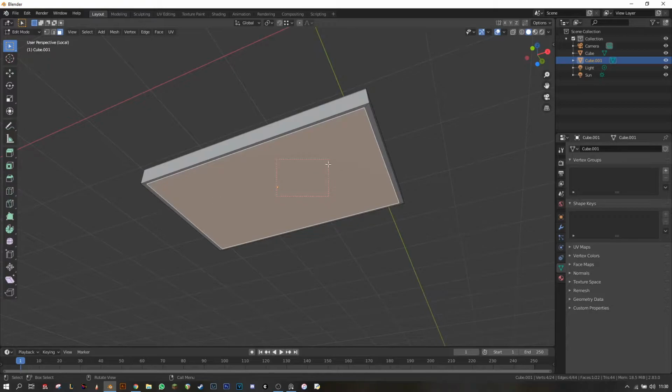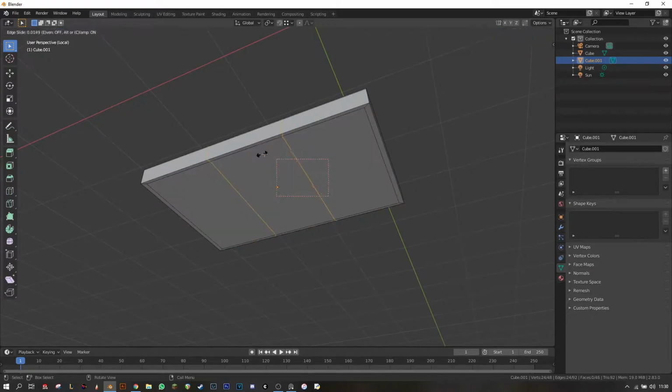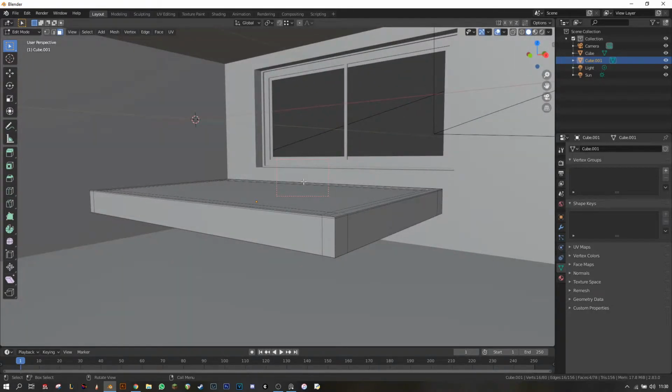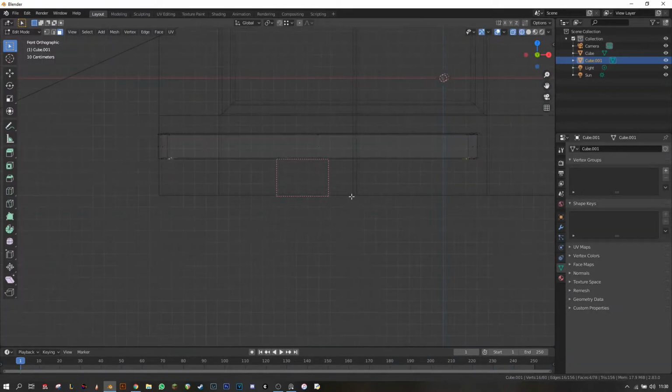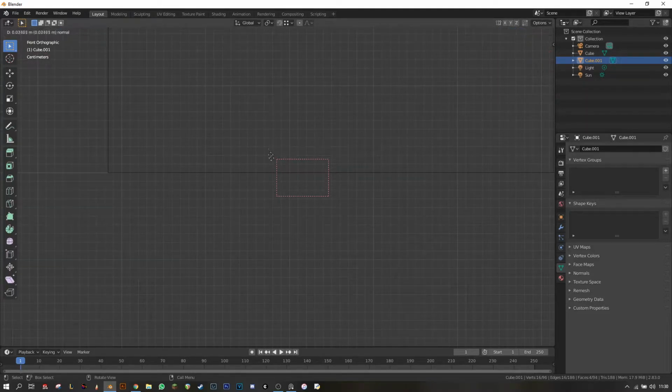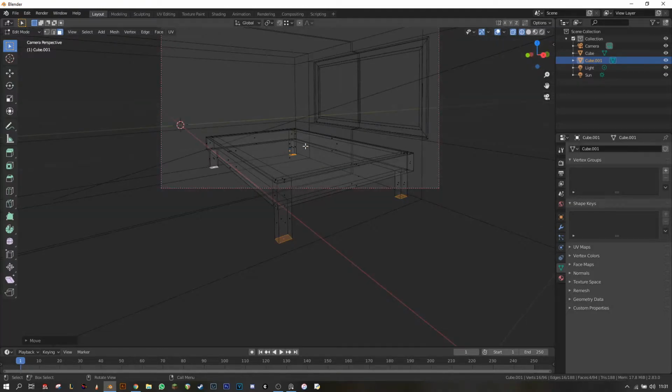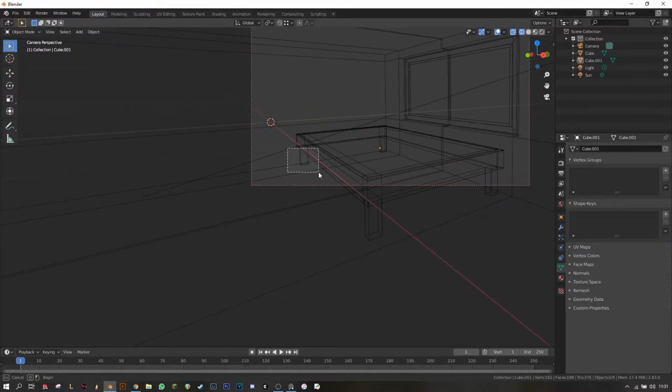So now you want to make the legs of the bed. So I'm going to add a couple of loop cuts, scale those out on the x-axis, put them about there, a couple more loop cuts on the y-axis, and then I just select these faces which I've made on the inside. Actually, I'll go into slash so that I can see the floor again and go into wireframe, because now I can press E to extrude them down and then just put them right next to the floor. You don't want them going through the floor, because obviously in real life they'll have a slight bevel on the edge, which is too small to notice in this scene, but they will have a very slight shadow on the sides, which you can actually tell if you use that Control B again to just highlight a small section.